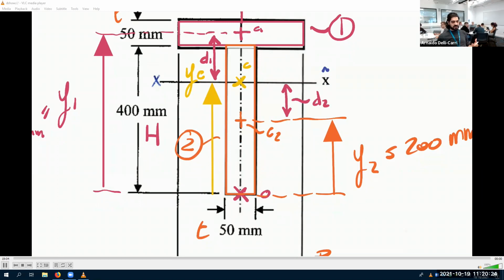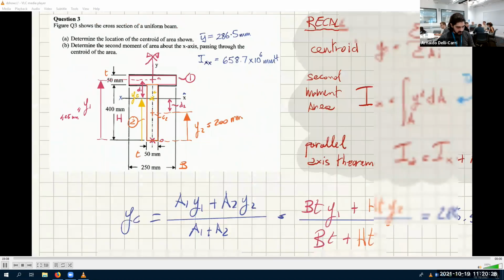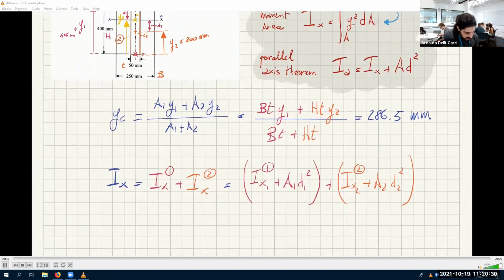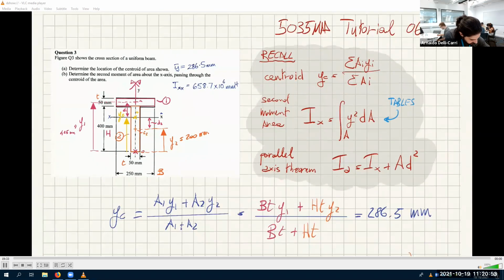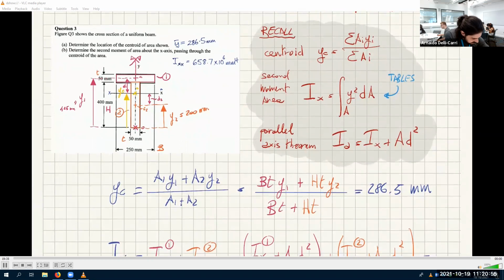Agreed? The distance between the two centroids, basically. All right, let me split this equation once more. I know this one is bh cubed divided by 12, and this one is bh cubed divided by 12, just a different b and different h for each. So this becomes: b for rectangle 1 is just capital B, and h is t.